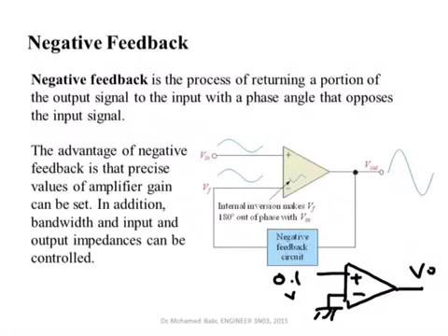So an OpAmp by itself is not really that useful for amplification unless we introduce the concept of negative feedback. Negative feedback is when we return part of the signal in the output to the input, here to the negative terminal. As I will show you in a number of examples, this guarantees that you can get precise amplification of your signal.